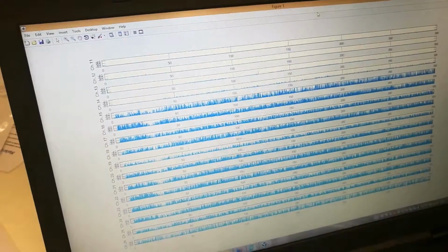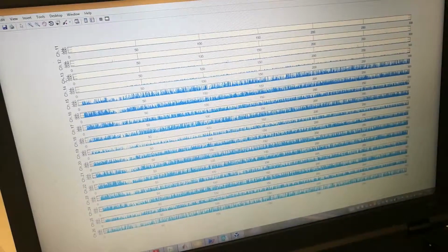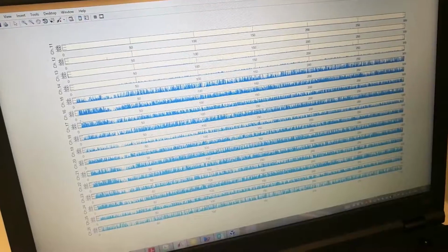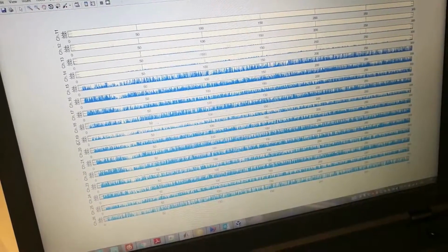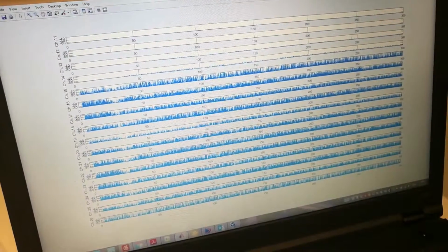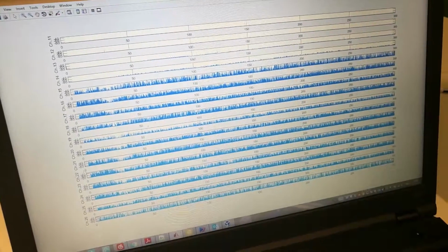There is barely any Bluetooth interference in the first four channels. As you can see, they are almost zero. Meanwhile, the usage of different parts of the frequency band by Bluetooth is not uniform. As you can see, the signal power in channel 19 and channel 22 is so different.